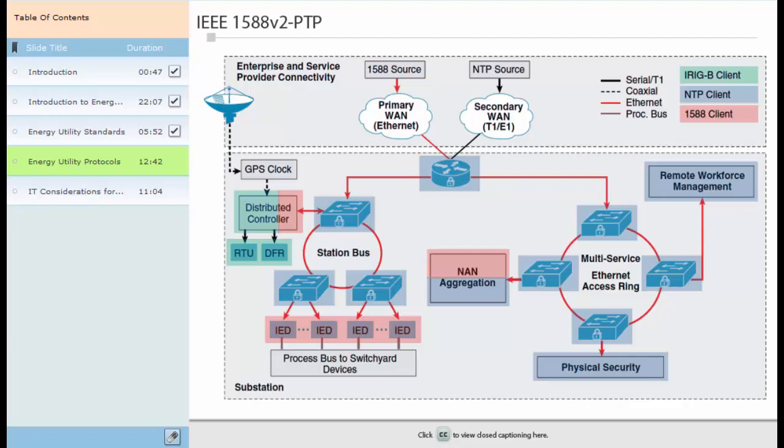Phasor measurement units continuously measure voltage and current, as well as frequency of transmission lines. Measurements are time-stamped and sent to a centrally located PDC for further analysis. It is also important to synchronize timestamps from all substations and provide measuring accuracy of within 1 microsecond to perform accurate phasor analysis. Accurate clocks enable sophisticated analysis of real-time and post-disturbance faults and events within a short amount of time. This leads to faster and more reliable fault isolation and resolution, and better planning of transmission resources on the electric grid.